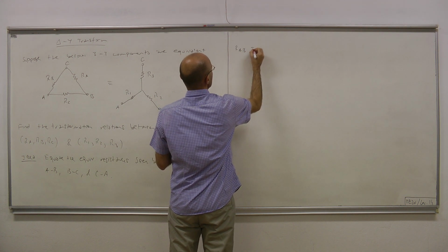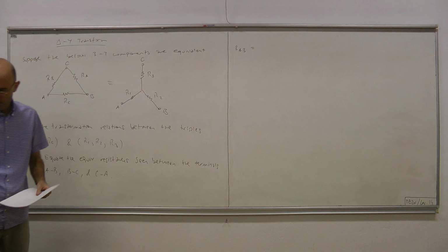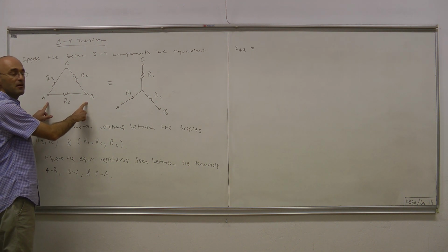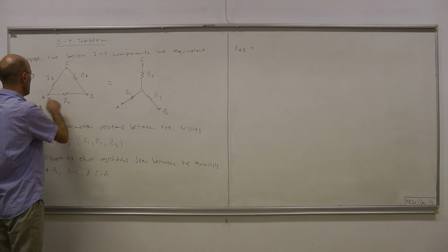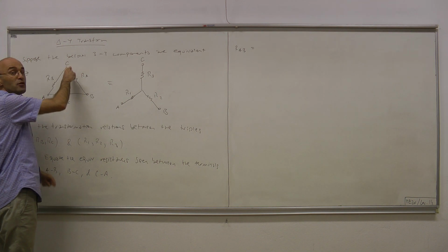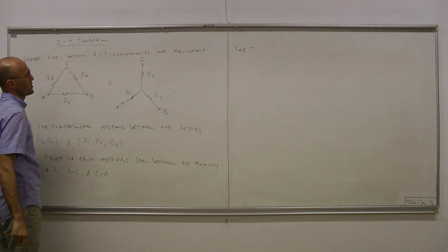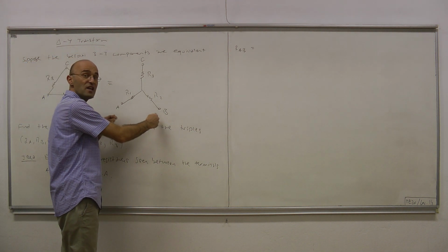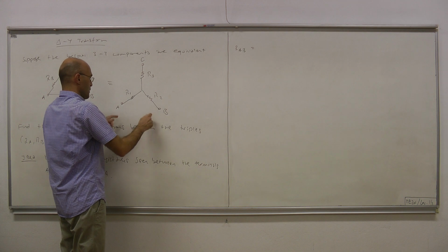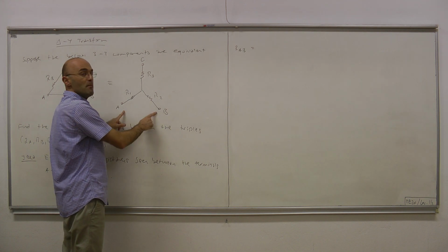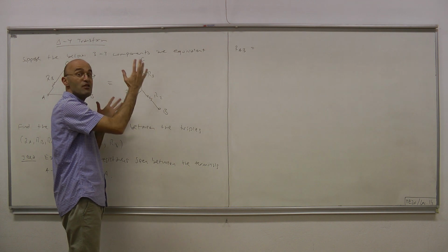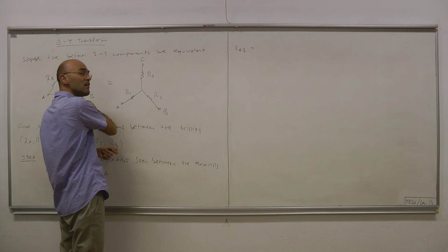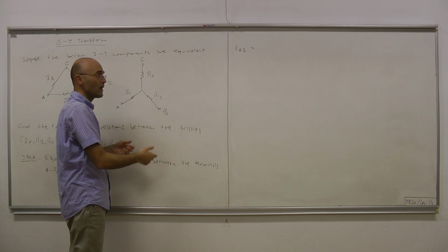RAB: I'm measuring the resistance from the pair of terminals A, B here. So I connect my ohm meter to that pair of terminals, and while doing that, I do not connect anything to terminal C. And I read something, let's say 17 ohms. If this is equivalent, and I do the same procedure here, connect an ohm meter between the terminals A and B, leaving this terminal open, unconnected, I should measure the same thing that I measured here, let's say 17 ohms.